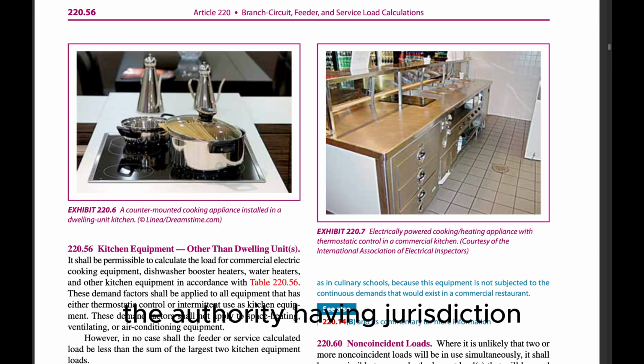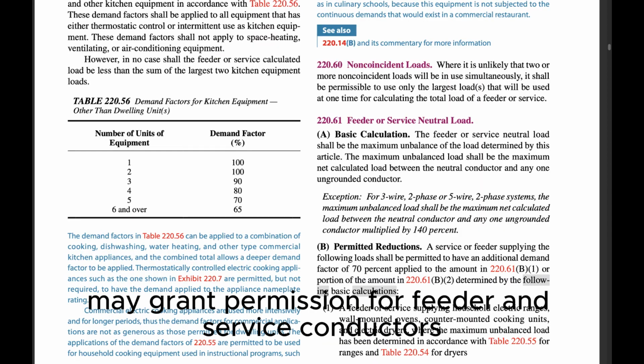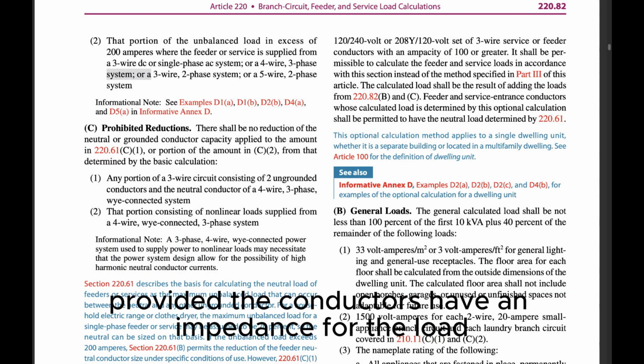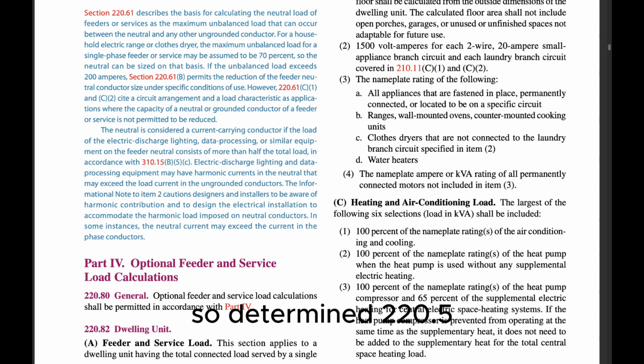The authority having jurisdiction may grant permission for feeder and service conductors to have an ampacity less than 100%, provided the conductors have an ampacity for the load so determined.